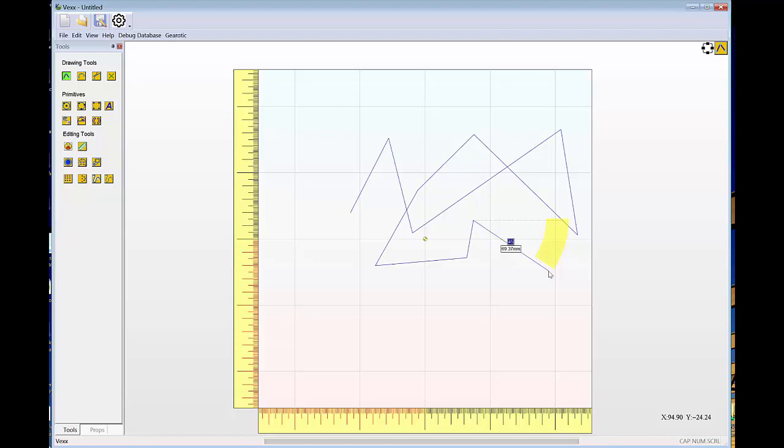I can change that and type the number 45 and hit enter, and now my line will be constrained to a 45-degree angle. You can see wherever I move my mouse, the line will always be at 45 degrees because I've locked that in. If I hit tab, and I then tell it I want a particular length, in this case type 150 for example, and hit enter, that line gets completed at 45 degrees with a set distance that we typed into the tips. So whenever you see tip boxes on the screen, you're free to hit tab to select between the tip boxes and simply type a number and hit enter to lock that particular entry so that it will apply to the current entity that you're drawing.